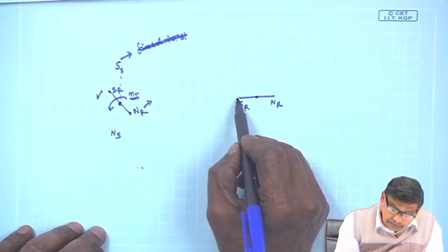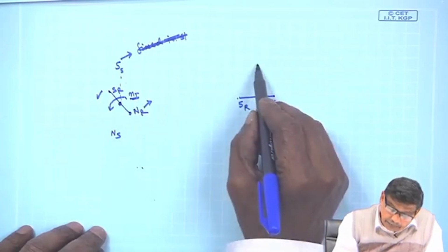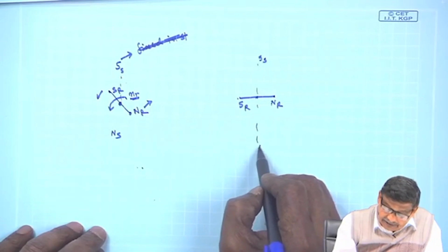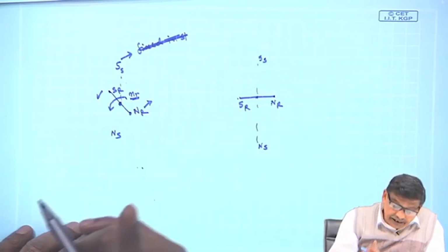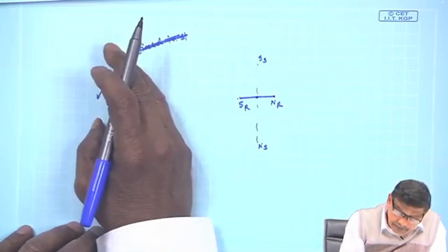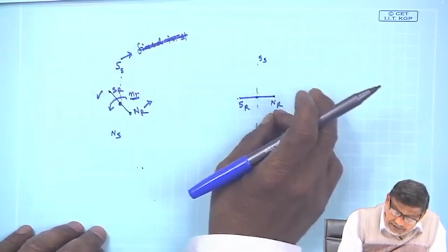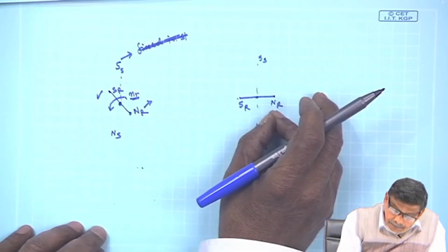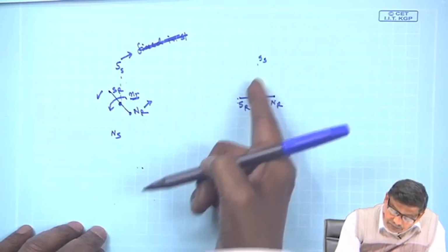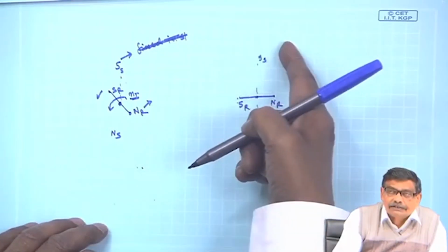Suppose the rotor poles come here, and the stator poles were earlier here, SS NS, and if I demand whatever torque it was producing at this instant of time, some time elapses, the rotor poles come here, SR NR, then obviously once again the same torque exists here, but the magnitude of the torque depends upon how far this SR is from SS.